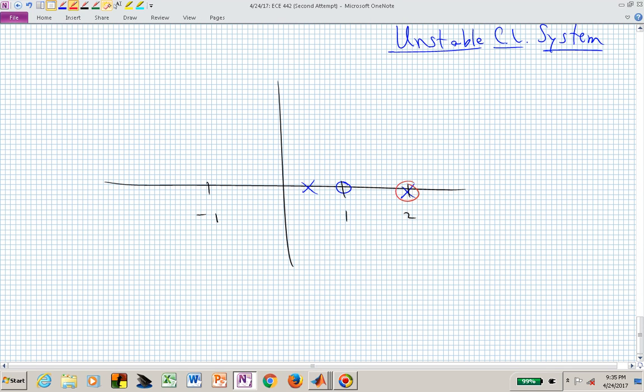Well, you might say, oh, that looks like a great idea, but in fact, that would cost you 50 points on a 2-point problem, and we know not to cancel poles or zeros outside the unit circle. But that does not mean that we can't introduce poles and zeros outside the unit circle. Suppose we put a 0 right there. What does that do? Well, now we have this segment, and again, we're stuck between the pole at 2 and that 0, let's say at 1.5. So a 0 introduced between the 1 and the 2 is not going to work.